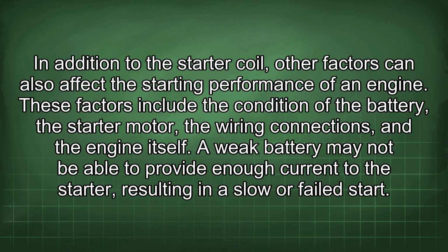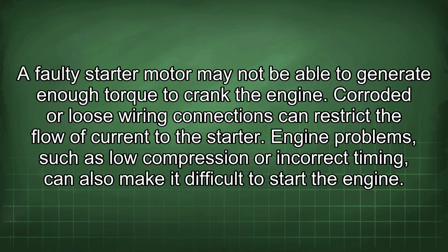In addition to the starter coil, other factors can also affect the starting performance of an engine. These factors include the condition of the battery, the starter motor, the wiring connections, and the engine itself. A weak battery may not be able to provide enough current to the starter, resulting in a slow or failed start. A faulty starter motor may not be able to generate enough torque to crank the engine. Corroded or loose wiring connections can restrict the flow of current to the starter. Engine problems, such as low compression or incorrect timing, can also make it difficult to start the engine.